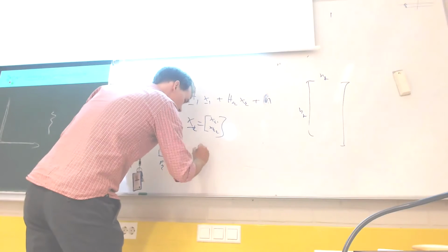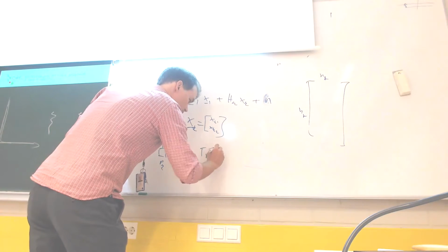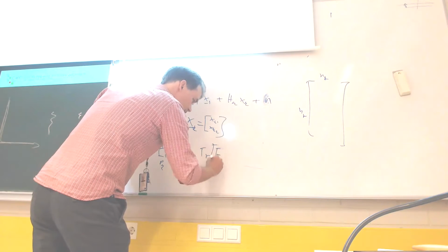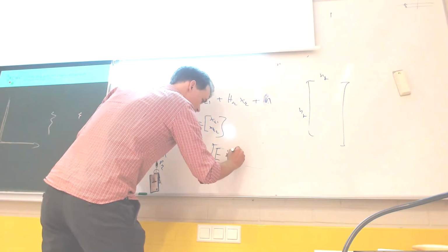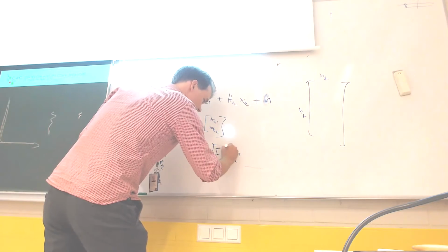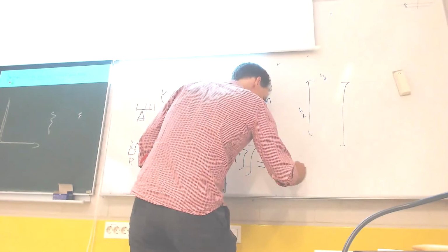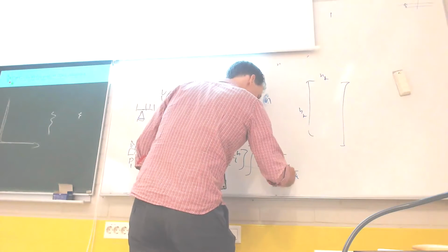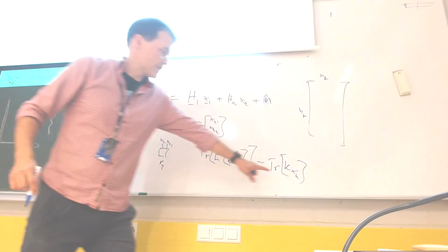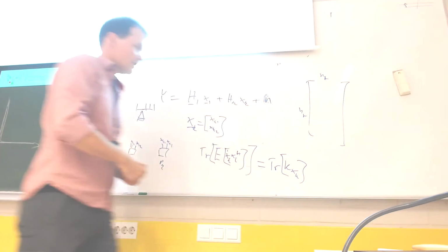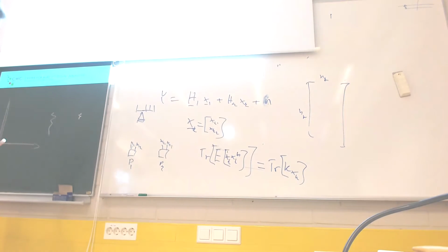So this is basically taking the covariance matrix, trace of x_k x_k Hermitian, which is the same as trace of the covariance matrix of user k. So the transmitted power, which is basically trace of the k-th transmit covariance matrix, is upper bounded by the user-specific power constraint.